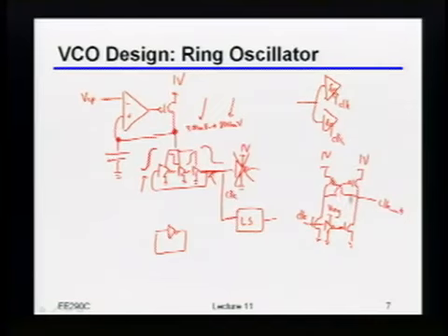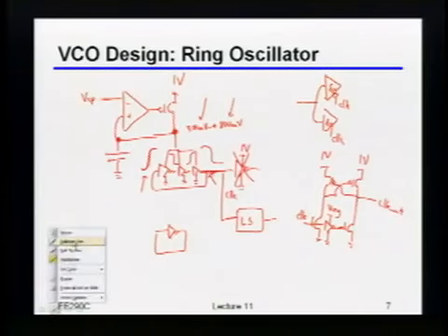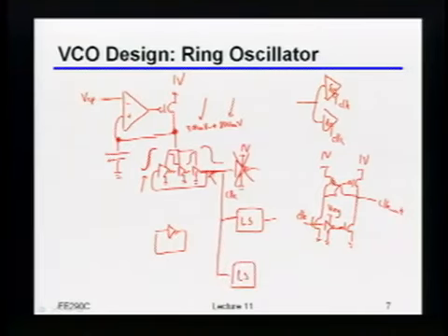So if you really wanted to do something like this, what you'd probably have to do is build 2 level shifters, where for one you take the bar output versus the other. Each individual duty cycle would still be wrong, but at least the rising edge to the rising edge would be the same. In general, you have to be careful anytime you do these level shift kind of things. And okay, I see some confused looks.